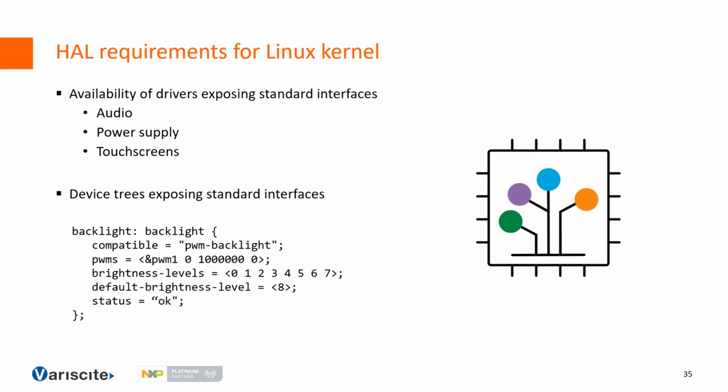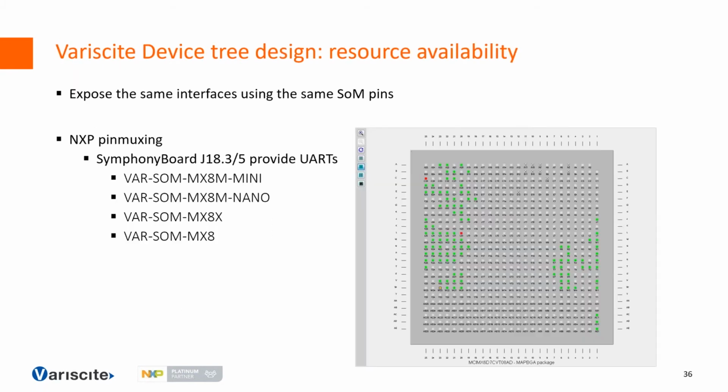You don't have to care and deal with the specific hardware aspects. Just as an example, here we report a backlight in the device tree. This backlight will be exposed in the virtual file system as a file that you will be allowed to edit, changing the value that represents the actual backlight. You don't have to deal with how this is happening.